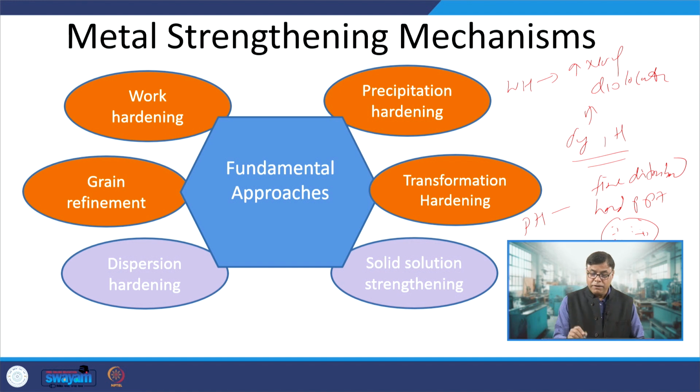Likewise, when the metal is subjected to severe plastic deformation, again these get fragmented and dissolved. This leads to softening, a drop in yield strength, and increased ease of deformation due to the reduction in yield strength.